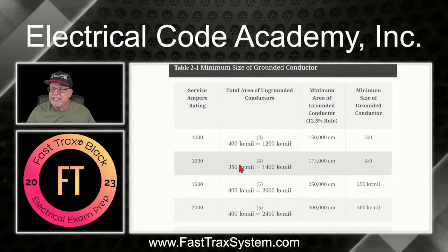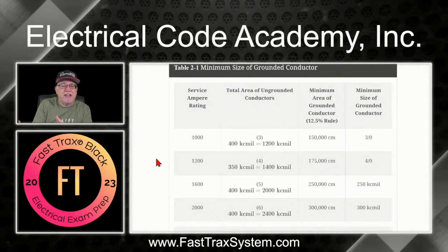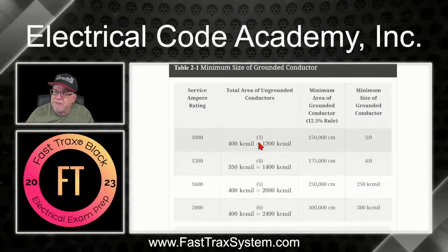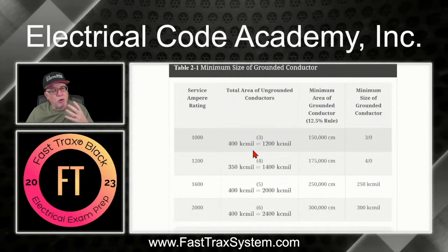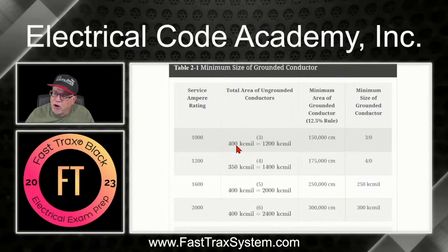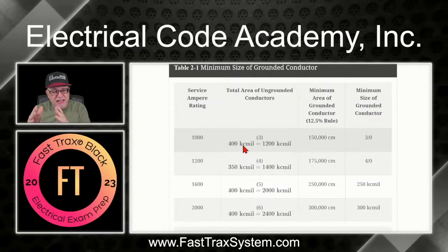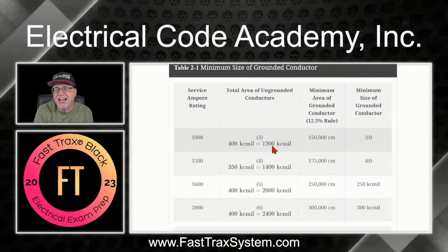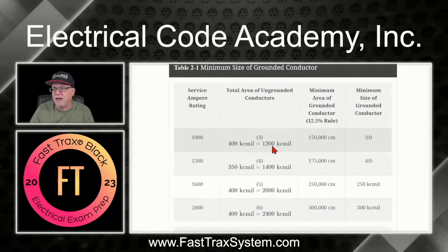So here are some rules of thumb. These are actually calculations that we're just saving you the legwork on. If I had a 1,000 amp service supplied by 3 sets of 400 kcmil, you just take phase A from each one of these sets. 400 times 3 is 1,200. Now 1,200 does exceed what? 1,100 kcmil of copper. And we're assuming copper unless stated otherwise.